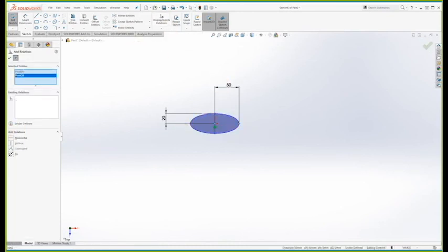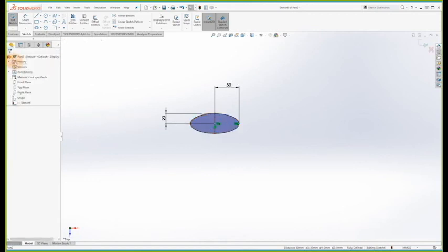And all we have to do is a relation here, just to show you. I could have just done this one here with this point here, and just make it horizontal, and it's going to fully constrain it. Because all that's missing is it wants to know what angle you're going to place it at. And if I'm making them horizontal, that's all you need for it to be fully defined. All right, so that's what I want to show you guys for adding dimensions with the sketch.